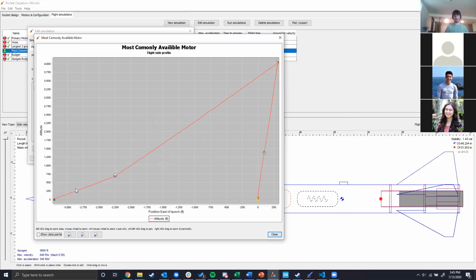And so it's a good idea to go and simulate. But before you actually go to a launch site, go figure out how far you can reasonably drift at that launch site, and then try to simulate and find the maximum safe wind speed you can launch in. And that's something useful you can use to prevent yourself from flying into a tree.